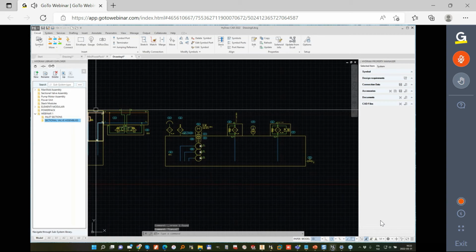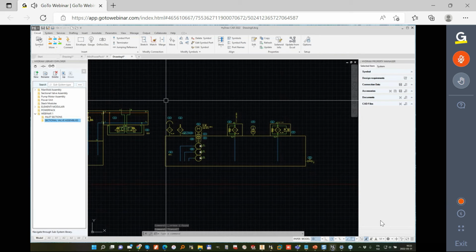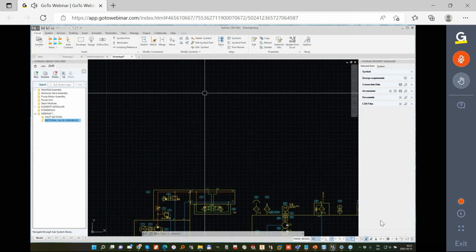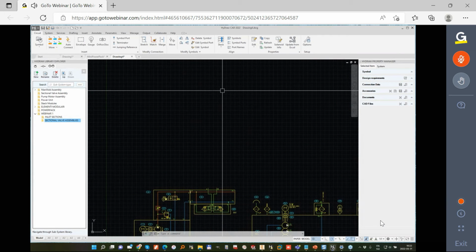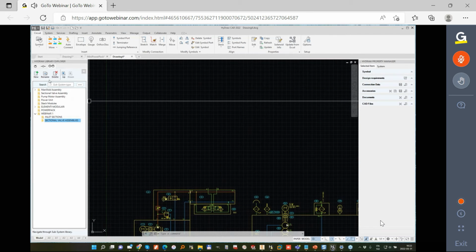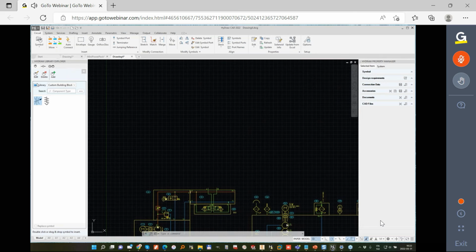Another good application is exactly the sectional valve assembly, where you want to have a complete symbol treated as one item, but you also want to control which slice you want to have in the subsystem. So if we want, we can do that. Let me go to the sectional valve symbols. I take some. Well, this is actually already an assembly.